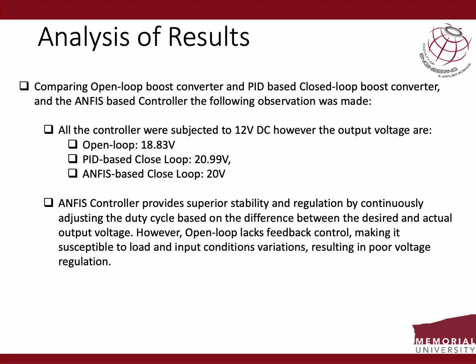However, the ANFIS based closed loop converter gave us 20 volts, and that is probably because, one, we picked data from the PID based controller, and the ANFIS was able to fine tune the results for us to attain the required 20 volts.